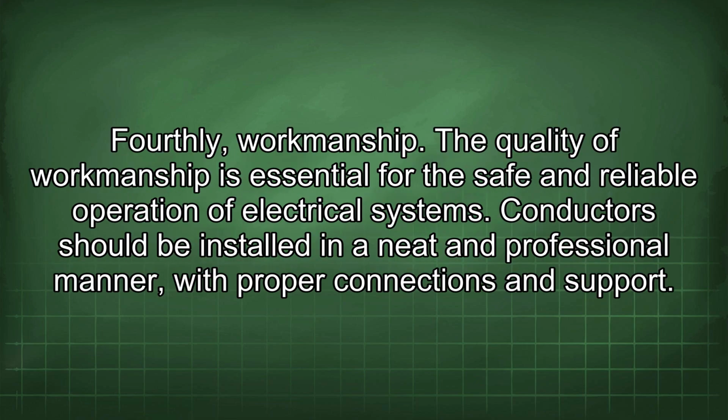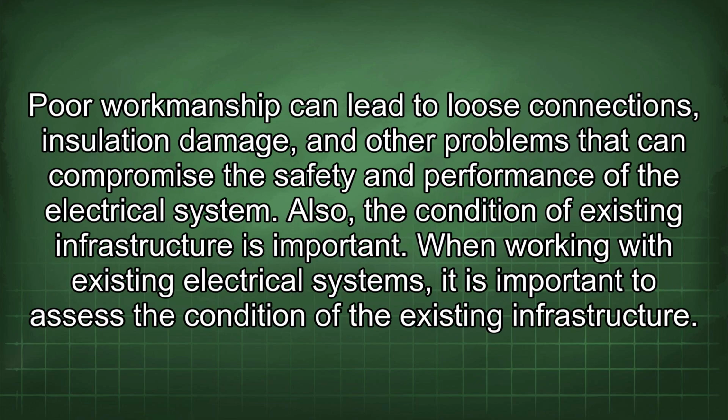Fourthly, workmanship. The quality of workmanship is essential for the safe and reliable operation of electrical systems. Conductors should be installed in a neat and professional manner with proper connections and support. Poor workmanship can lead to loose connections, insulation damage, and other problems that can compromise the safety and performance of the electrical system. Also, the condition of existing infrastructure is important.